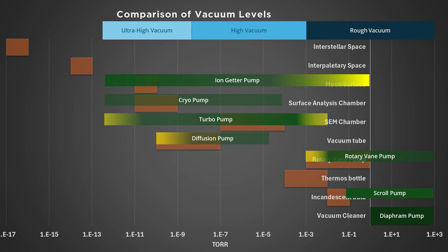well, let's say your turbo pump might be $25,000. So if you ignore the fact that the forepump is not working, you will burn up your turbo pump.